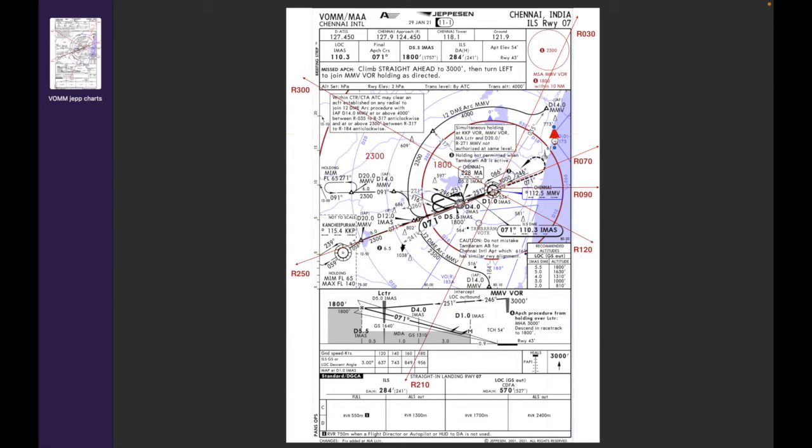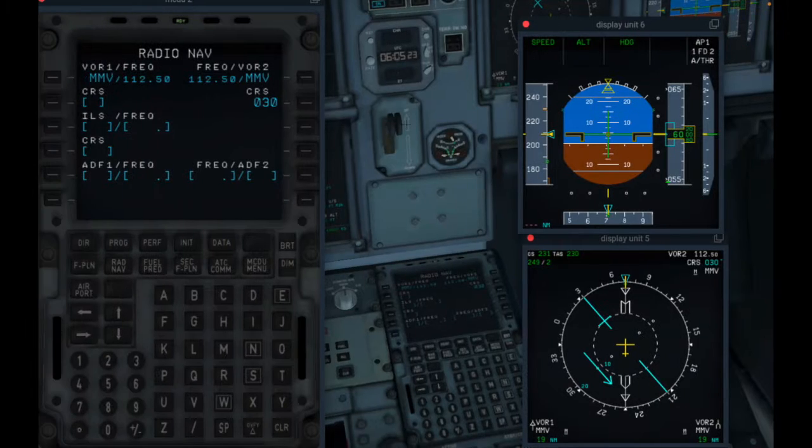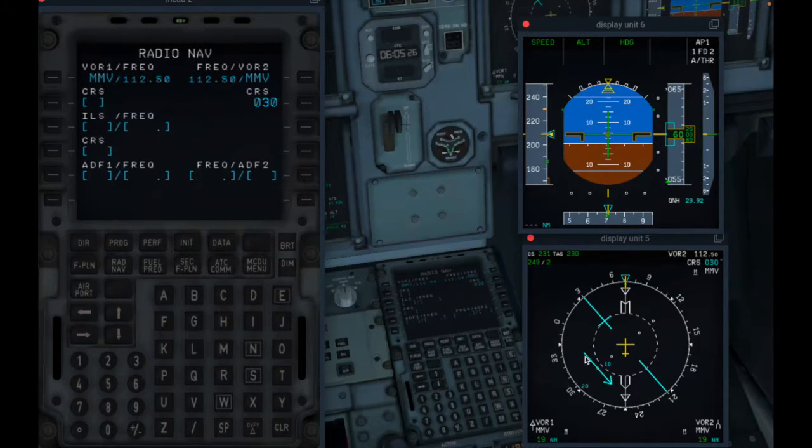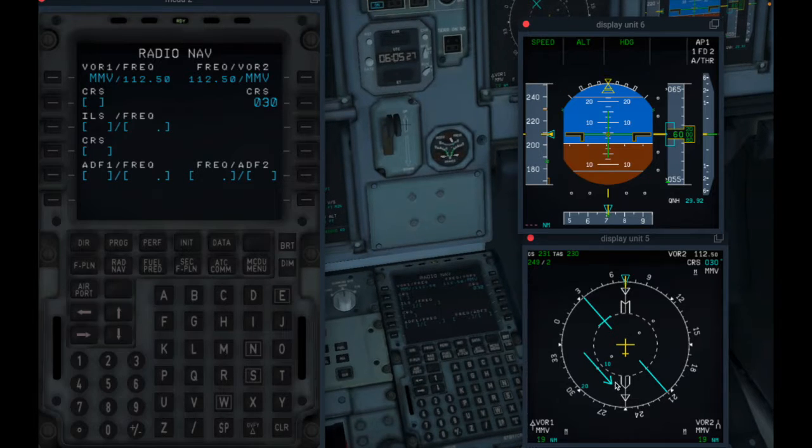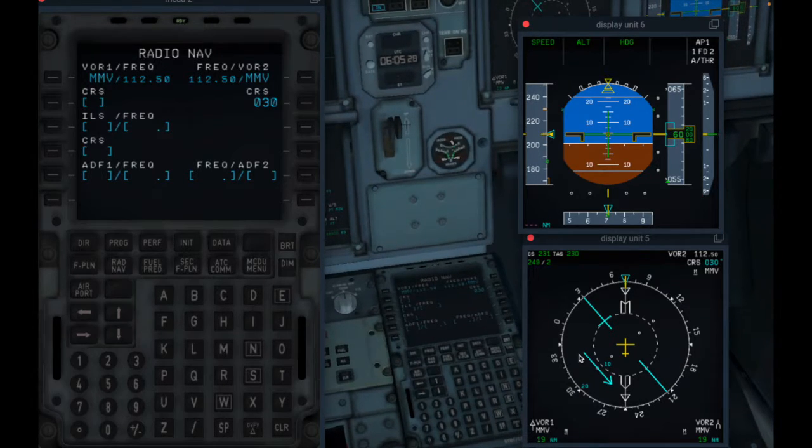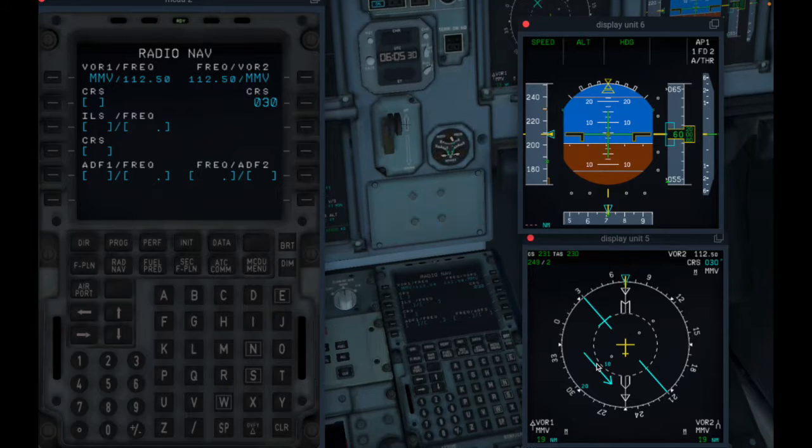So the aircraft will eventually intercept radial 030, right? And that's effectively what your course is telling you as well. You've selected that you want to fly on this path, 030, so the aircraft is telling you, please fly left. This arrow simply indicates where the VOR is. Forget about the arrow. The aircraft simply tells you, just fly left to fly on this course of 030.